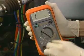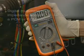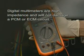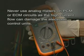Digital multimeters combine volt, ohm, and ammeters into one diagnostic unit. Digital multimeters are high impedance and will not damage a PCM or ECM circuit. Never use analog meters on PCM or ECM circuits, as the high current flow can damage the electronic control units.